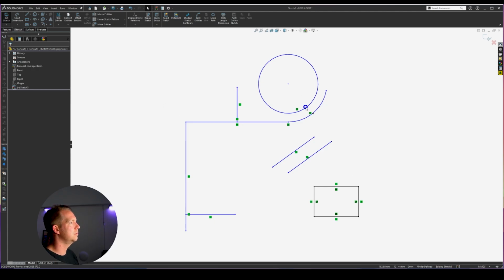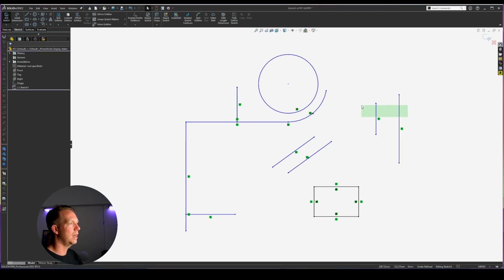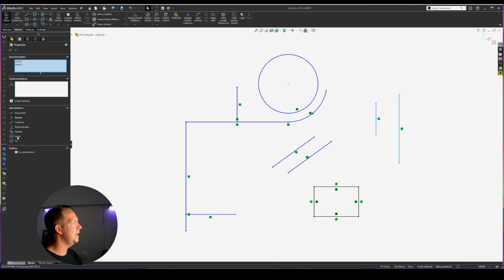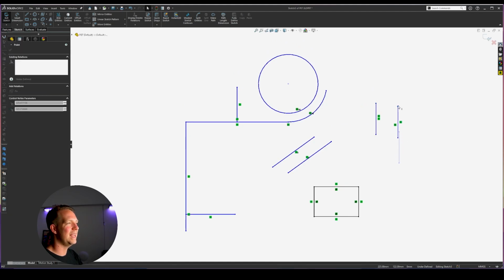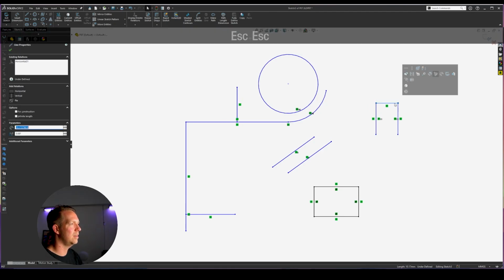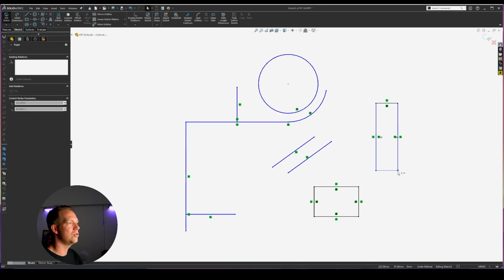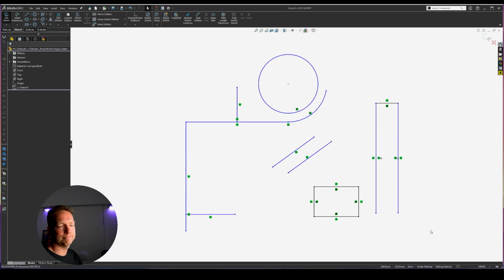There are also relations that are related to dimensioning. One of those, let me show you another example. I can make these two lines equal. So that means they are equal in length. If these two are horizontal at this point here and this line happen to be fixed, I grab one line and drag, the other one's going to match it.